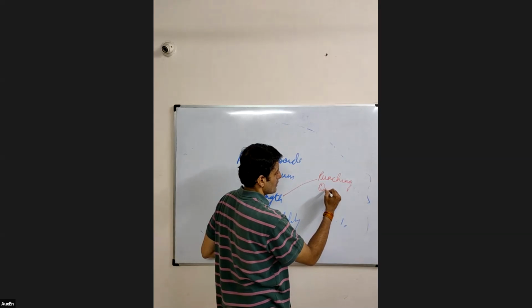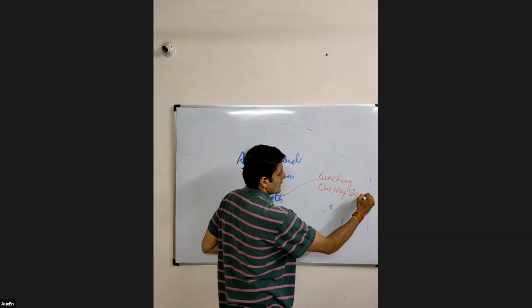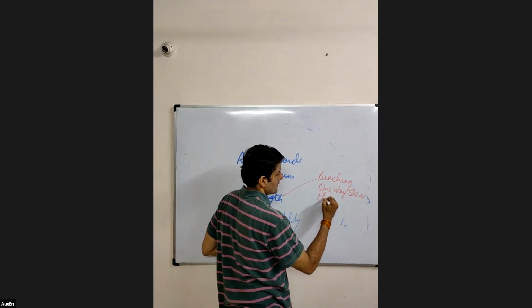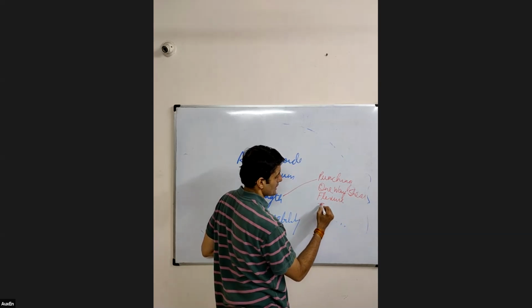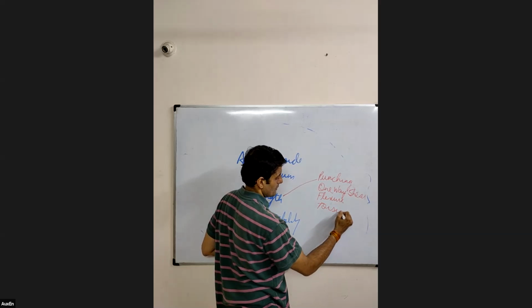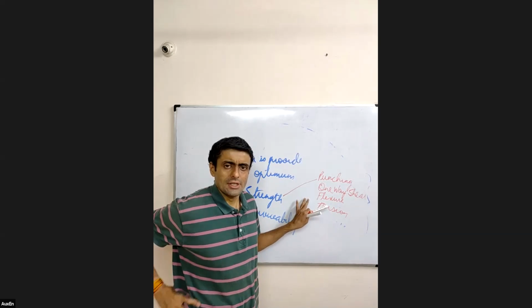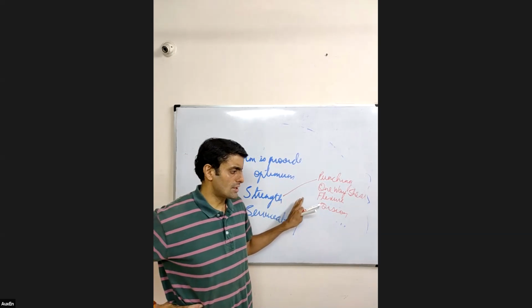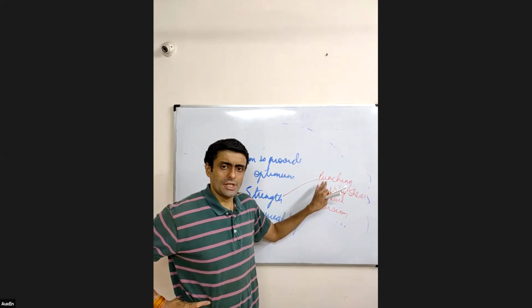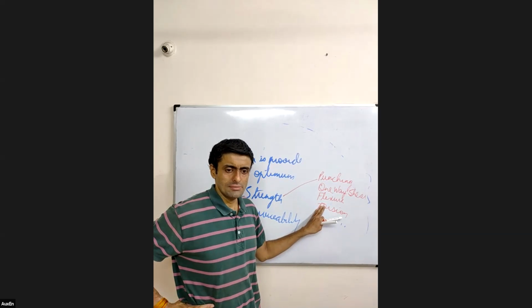I will check what is called one-way shear. Okay. I will check flexure, and generally there is no torsion as such, but I will check torsion also. So these are the major actions that I will check my flat slab for the strength criteria. So it is punching, it is one-way shear, it is flexure, and then there is an issue of torsion.